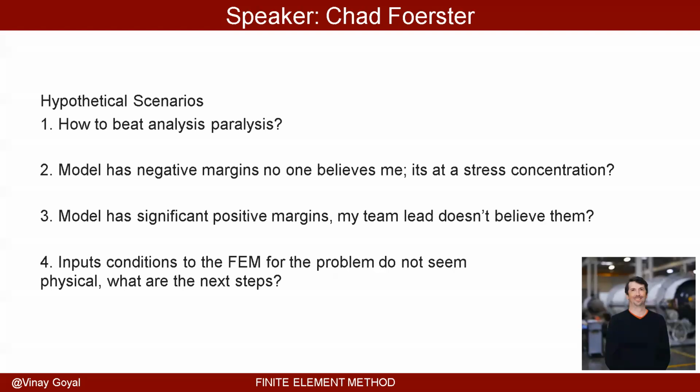So, bounding the problem. Go over here and ask what is the most simplistic thing you can represent this with. If it's a bracket with all these holes and fillets and all that stuff, can we just do a plate model with no holes and no fillets, connect a bunch of shell elements together, and just see what happens, right? So I throw the solid element model at the wall, and I work on my shell model, which is maybe a reduction. Sometimes shell models are not possible for certain things.